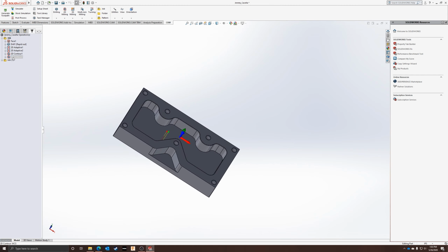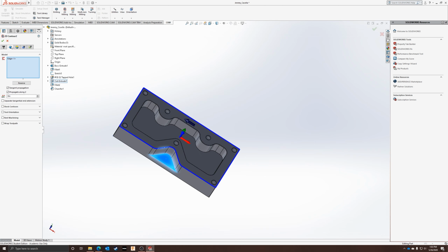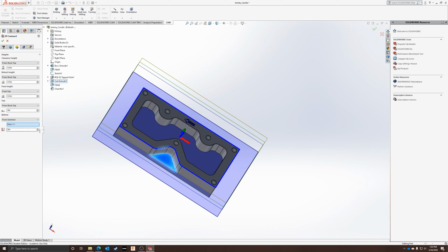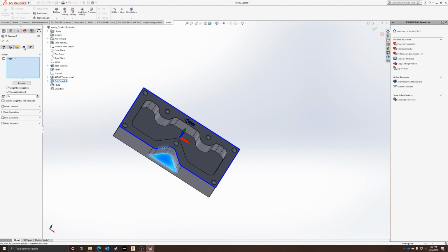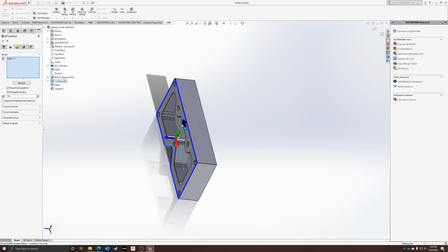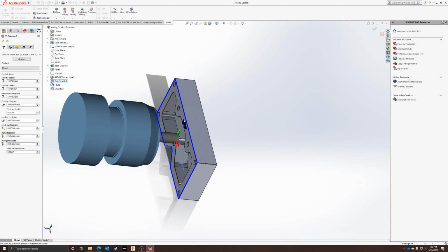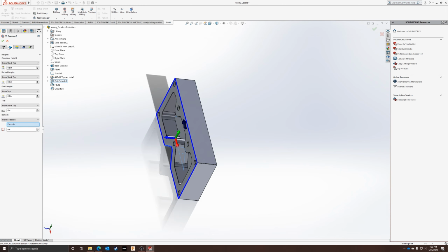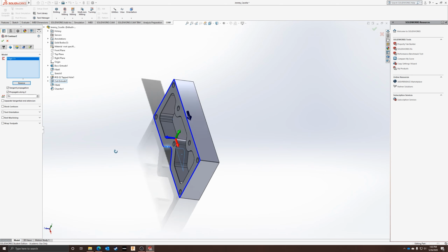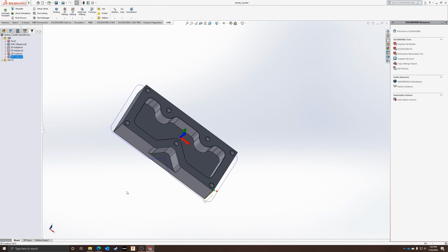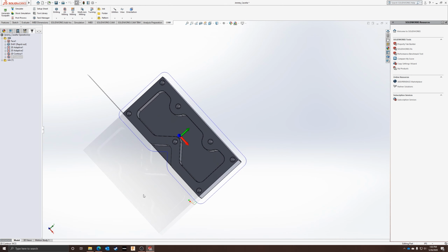If it works, right? And so let's look at it, see what's wrong. Why didn't it work? The tool is correct. The edge is correct. The selection is correct, and the depth is correct. Is it something to do with machine cavity? Let's look. Yeah, see now there's an arrow. Uh-oh, see that's the arrow I was talking about. What do? I reverse the arrow is what we want because it's thinking the inside when it contours. So I need to flip its direction. Reverse. Now it's on the outside. Problem solved. Right? If you don't see your toolpath, you got to think what's going on.